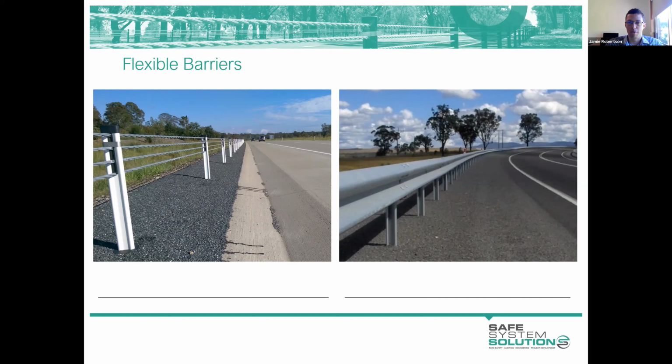If they're not anchored, there'll be some deflection. We sometimes see rigid concrete barriers used in temporary situations. In those cases, there'll be a small amount of deflection, but I would assume 0. But if it's not anchored, you ought to assume that it will move by some degree. But you would still allow a working width, a roll allowance, of heavy vehicles. Yeah, you ought to. You're right. We'll talk a little bit about that in a little while.